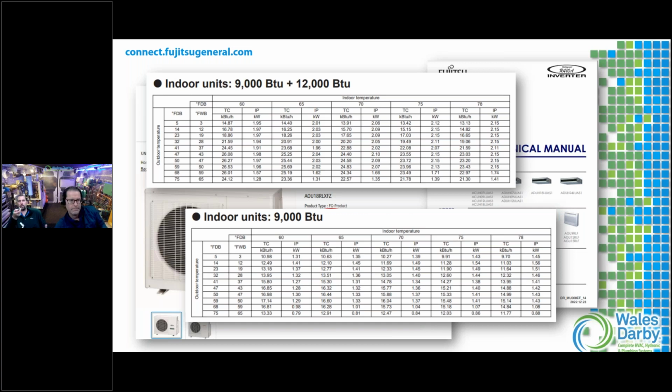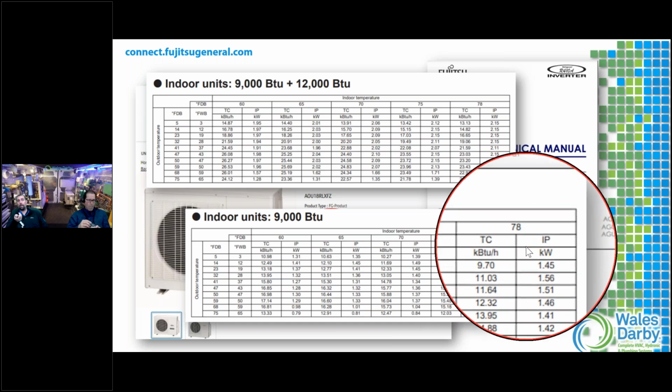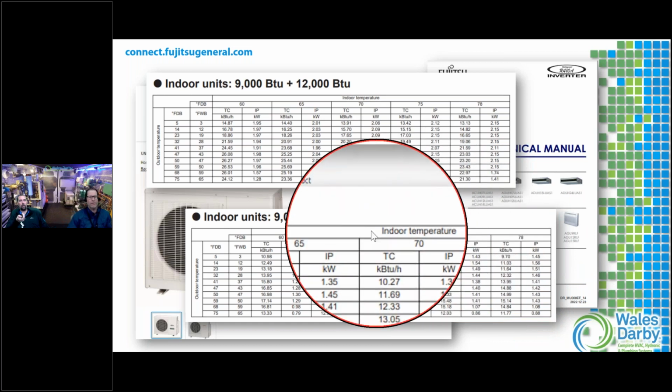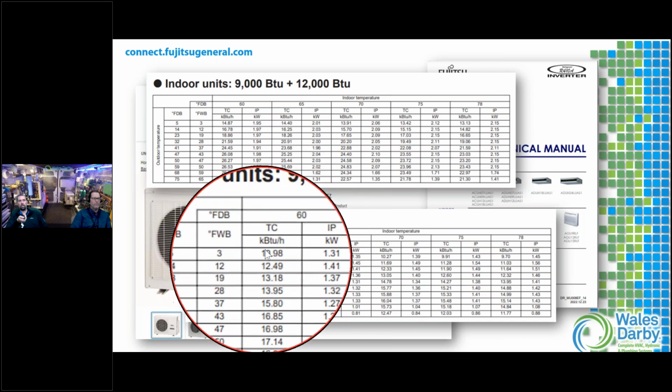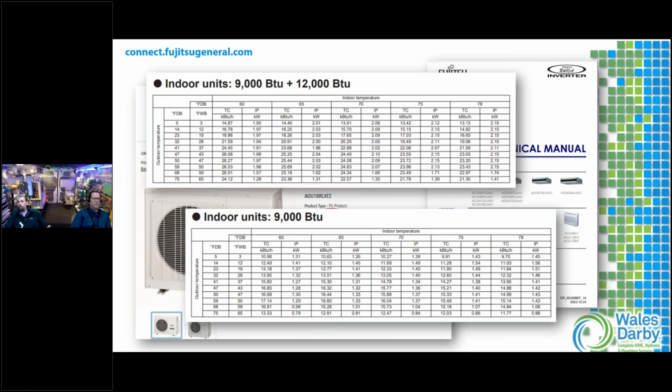And it's a good point, because you can see it right here. You're talking about indoor temps and how they can drive this. Here are our indoor temperatures. If I have cooler temperatures and more BTUs, the system's going to recognize a 60-degree indoor temp as a high load. So it's going to ramp up into these extra tiers, as far as the compressor. And to what Anthony's saying, the inverter side, we ramp up now because we need a lot of BTUs to cool the space with 60-degree incoming temperature into the heat exchanger.